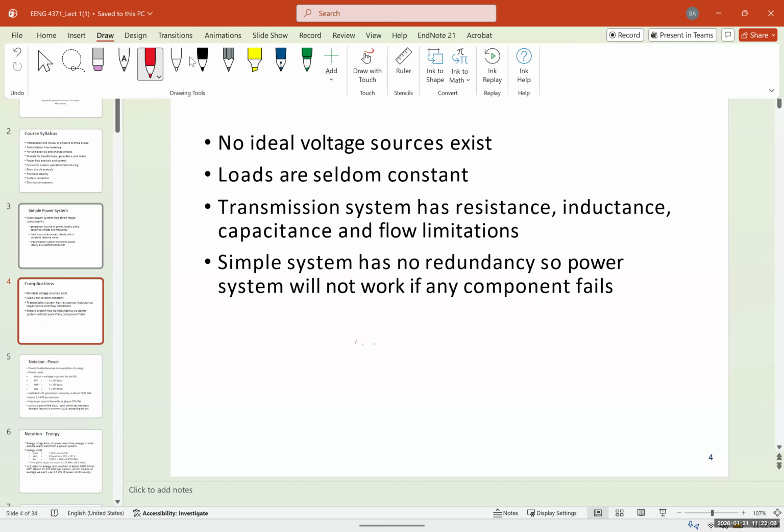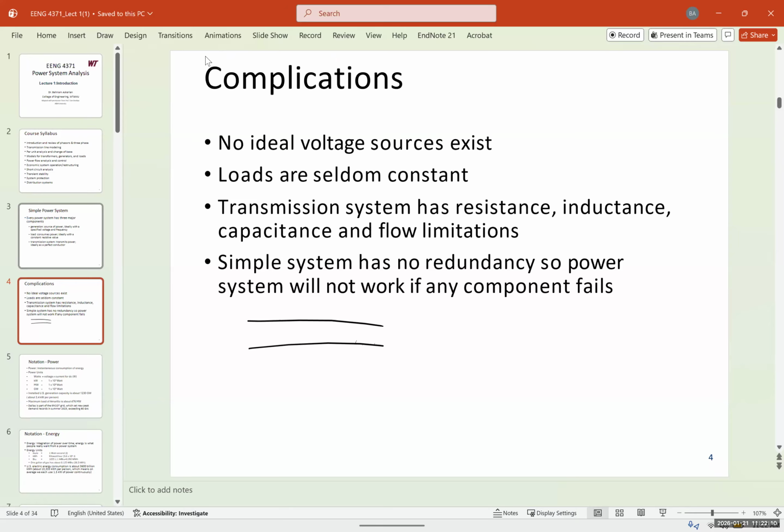But yes, as I mentioned, it could be between ground and one of the phases, or between the phase and the neutral, and if you have a middle pole, any of that creates some capacitance, depending on the frequency and what frequency it resonates. So you have capacitance and inductance.